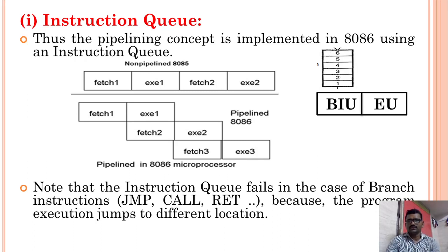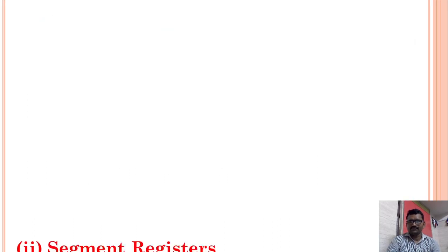So nowadays microprocessors are designed with a branch prediction logic circuit. With that circuit the time will be reduced. Not for all cases. If after execution of a branch instruction we get some address, and that address is the same as predicted, then the time will be reduced.